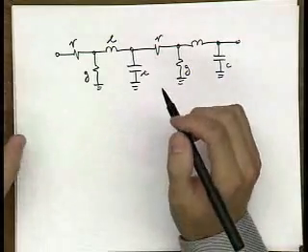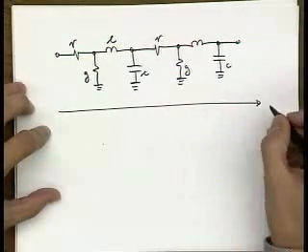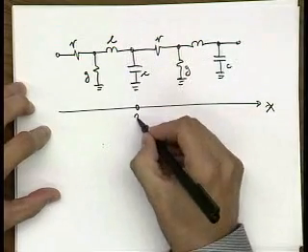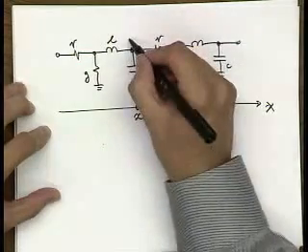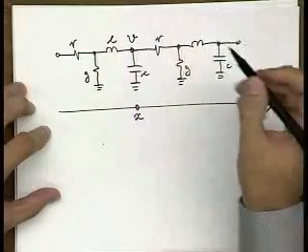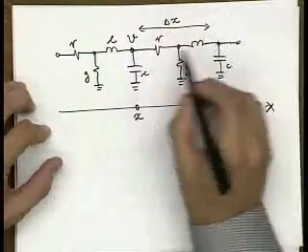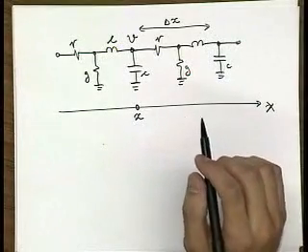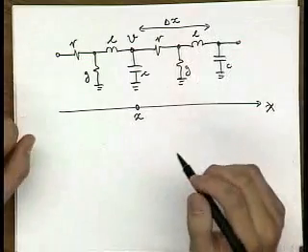So now let's analyze what happens at a certain distance x. If this is our x-axis, and let's say that at this point x we analyze this node and see what happens with this voltage V. And let's assume that this is delta x over here, because that's the one segment that you normally use to describe what's going on. You have resistance, conductance, inductance, and capacitance.